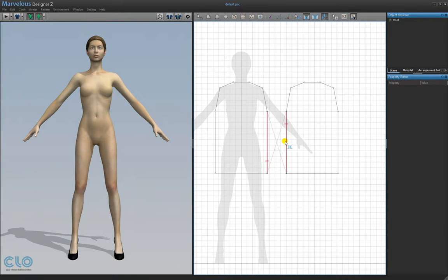Move the mouse over to the other end of the line and make sure the dotted lines are parallel, not crossed. When there are many seam line pairs, it may become difficult to tell if the dotted lines are parallel or crossed. In this case, you can also check the sewing notches that form along the seam lines to make sure they have been placed and matched correctly. Click the second seam line. Sew the rest of the seam lines in the same way.